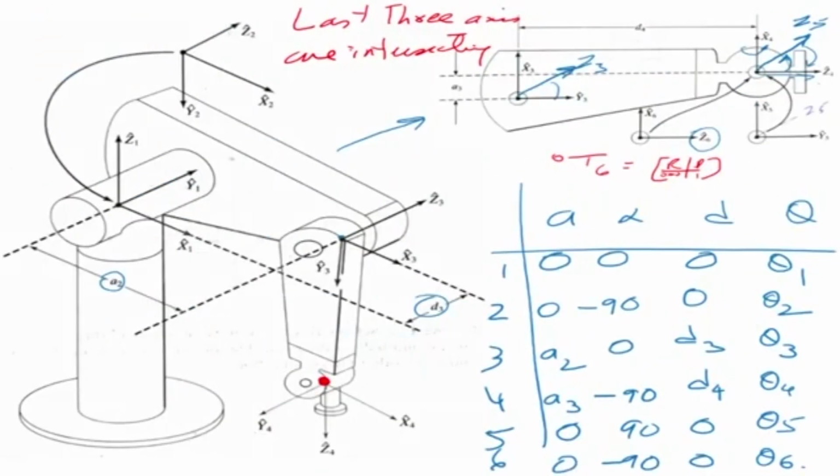So if you look at the manipulator structure and you look at the DH parameter table very, very carefully, we see that the 0 and 1 axes are here. 0 and 1 is here. 0, 1 and 2, all three are here. The 0, 1, 2 origins are there. They are the same point. Frame 3 is here, the origin of frame 3. Frame 4 origin is here. So on this figure, it is at that point. So the origins of 4, 5 and 6 are the same point.